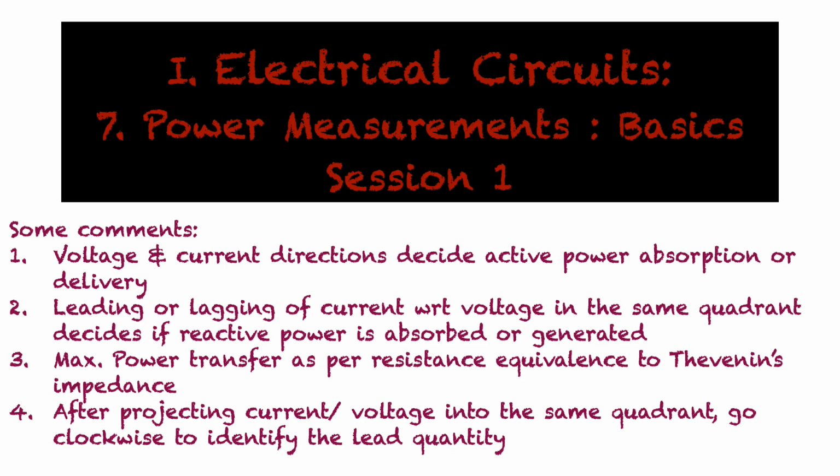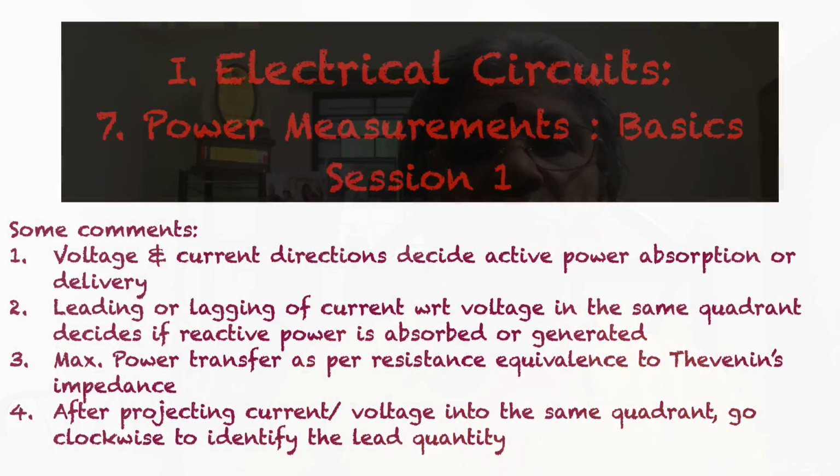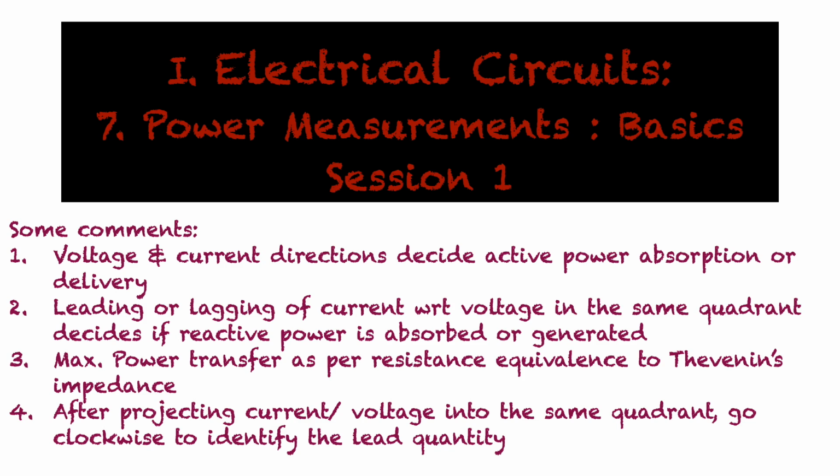On the other hand, if as you go in the clockwise direction, so long as they are in the same quadrant, you see the current phasor first, then we see that the current is leading, and this happens with a capacitive circuit, and so it is delivering reactive power. So this aspect also needs to be remembered appropriately.